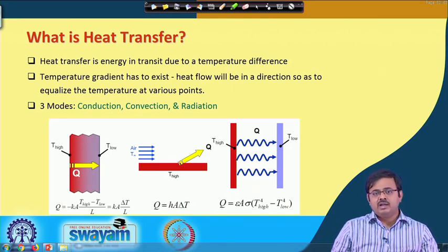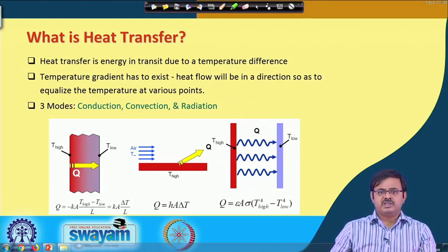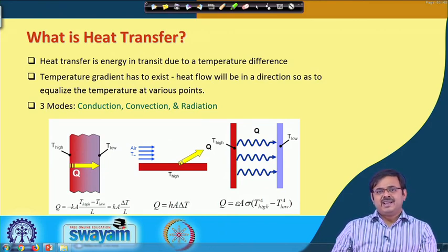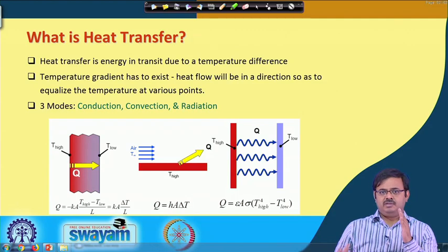When the emissivity is 1, it is known as a black surface, sometimes also called a black body, but when we talk about radiation heat transfer, it is more about surface. So, we will call it a black surface, and something whose emissivity is lower than 1 is a non-black surface. Okay. Emissivity can be a function of wavelength, and sometimes what we do is we take an average value of the emissivity over the range of thermal wavelength, and we give it a constant value, and that is called a gray body approximation.